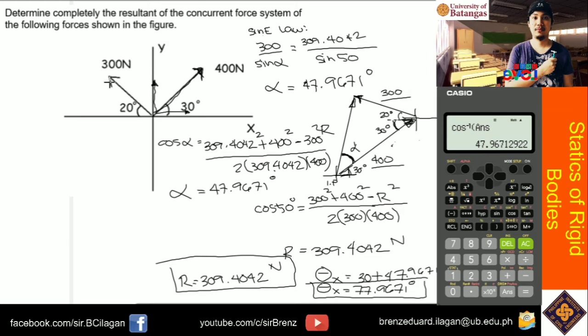Okay, how about the 300 Newton? Again, the 300 Newton is going up to the left. So again, up to the left, that is already its direction. So its y component goes upward, and its x component goes to the left.